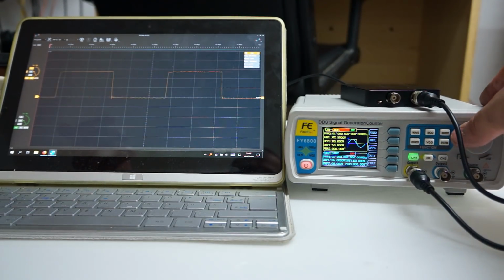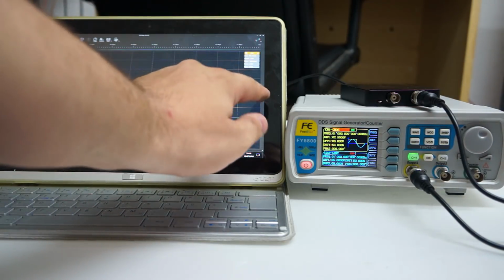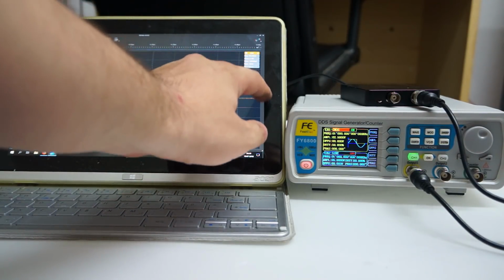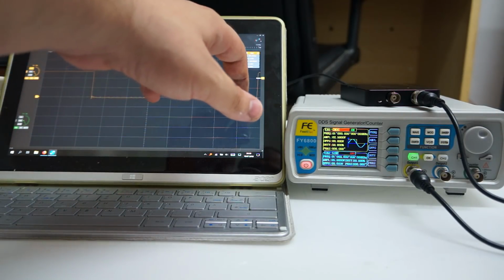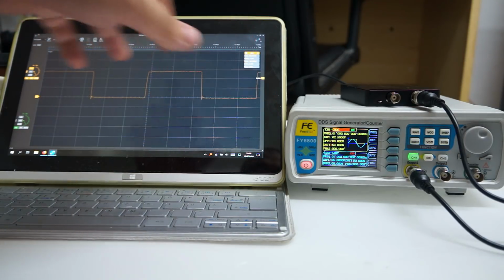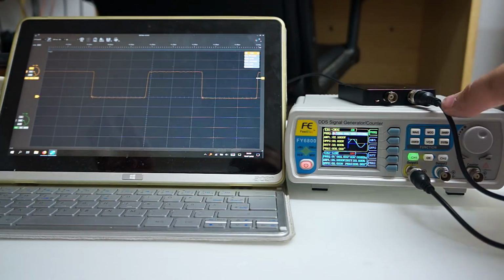Let's change it to a CMOS. As I told you, at the bottom, let's change the trigger to something better. The bottom is 0, which it actually is minus 240 millivolts, and the Vmax is 2.75 volts. The amplitude on the signal generator was also cut in 2.